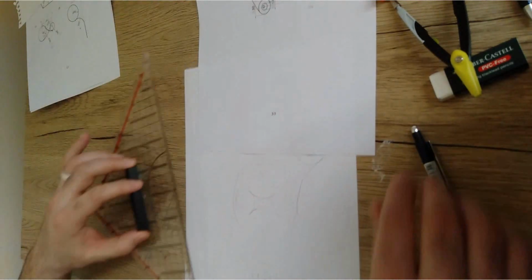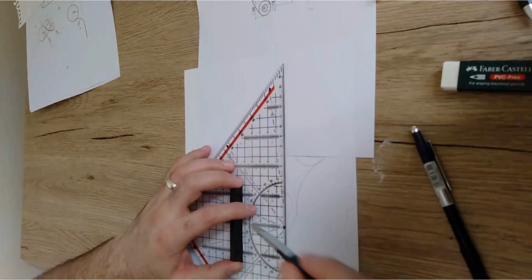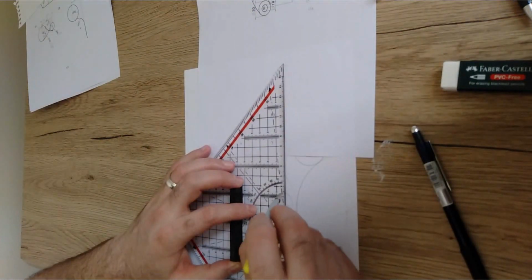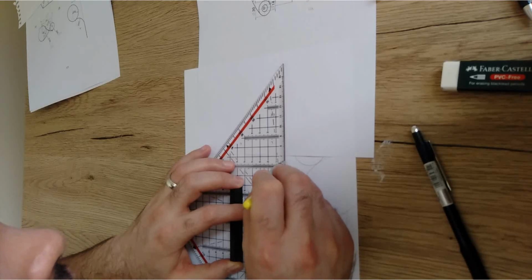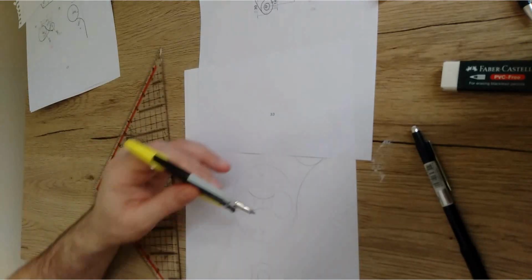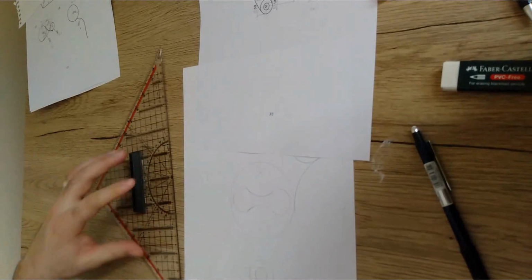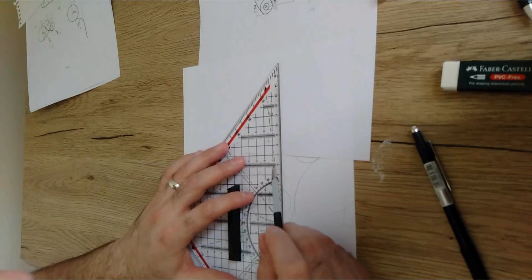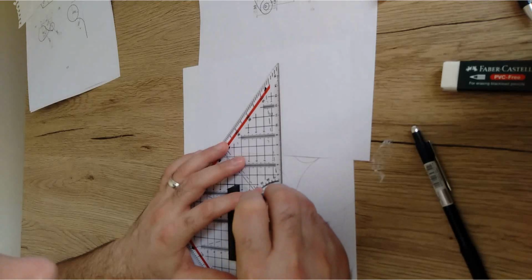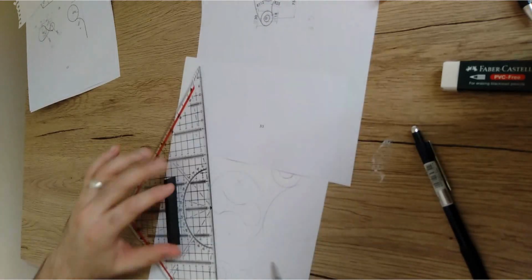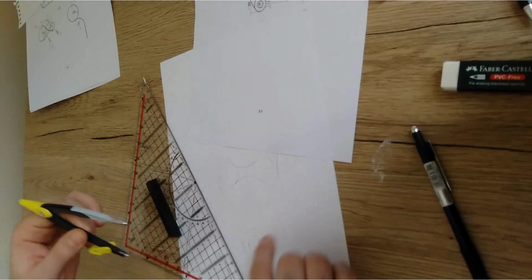So what I'm going to do is open the compass twice, from the center of the big circle and the small circle. I'm going to start with the 65, which should be drawn from the center of the big circle. Then I'm just going to draw an arc. This is going to be the first locus. Then from the center of the other circle, I'm going to draw a curve with a radius of 40, which is going to give us this curve. So this is the second locus.